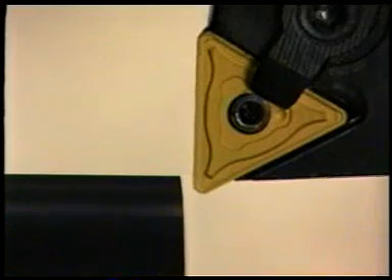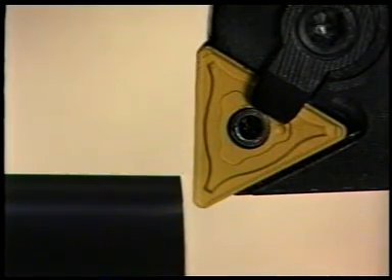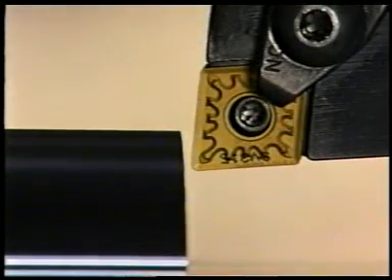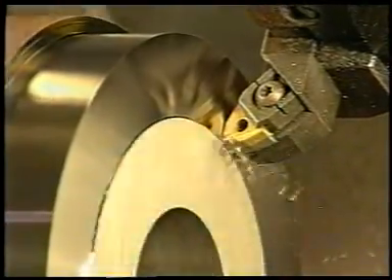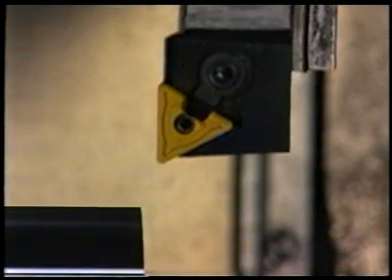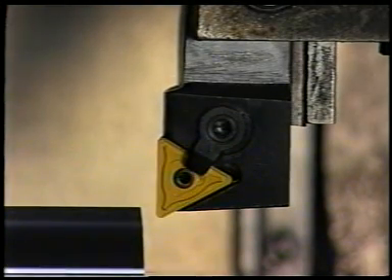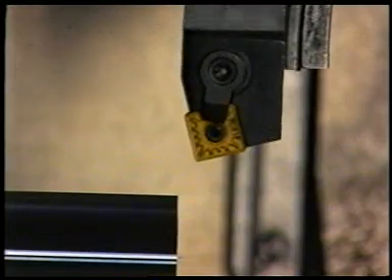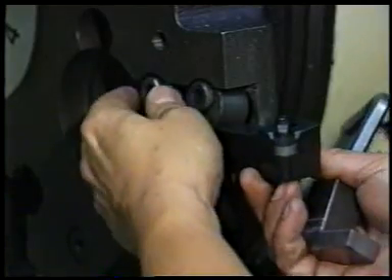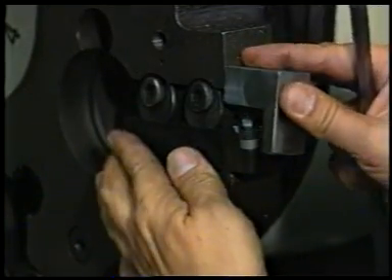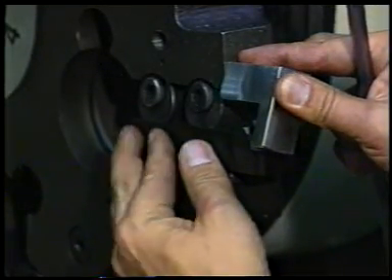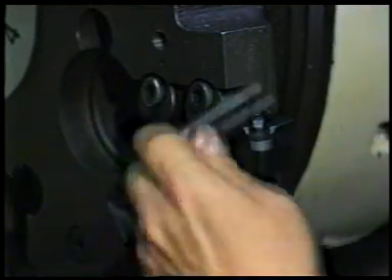When turning to a square shoulder, the tool holder should have a 0 degree lead angle or a -5 degree lead angle. In boring, a 0 degree lead angle is preferred, as it directs the feed force along the axis of the work, minimizing deflection. Some tool holders are designed for facing. The offset style tool holder lets work be performed closer to the chuck jaws and is generally chosen over the straight shank. Tool holders and boring bars should be positioned as far back in the turret or tool block as possible to maximize support. Overextended tools chatter and cause insert breakage.